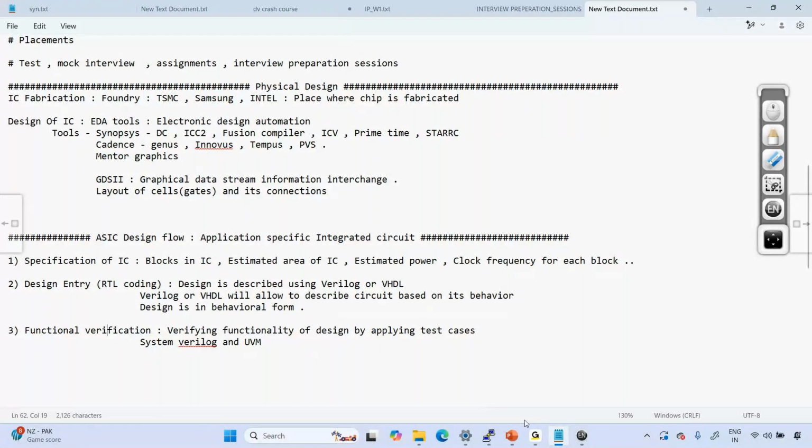They are not aware of what clock period is used in physical design while implementing the design. So there is no delay, right? Delay is not taken care of here. There is no cell delay. So how do you tell that this design is not working with the clock frequency? There should be cell delay, right? So during functional verification, they will not take care of cell delay. They assume there is zero cell delay, or no delay, or no cell at all.